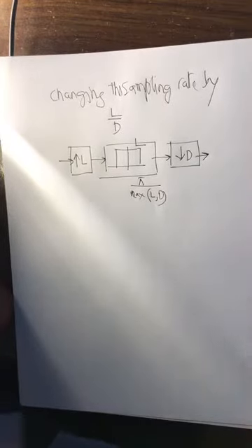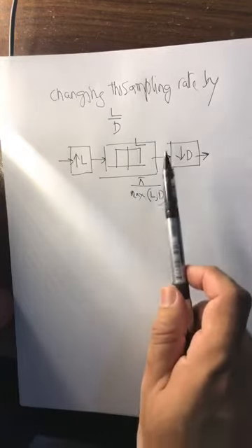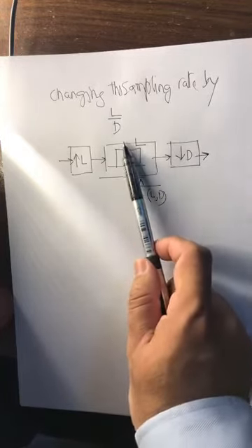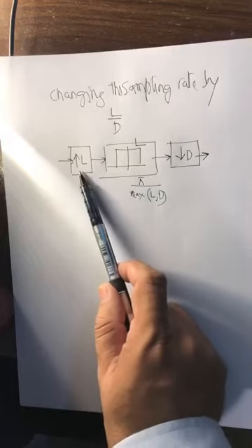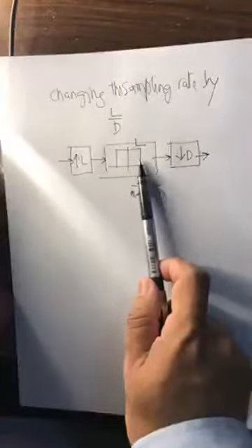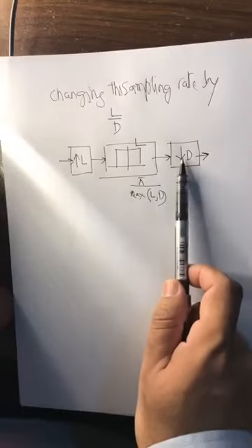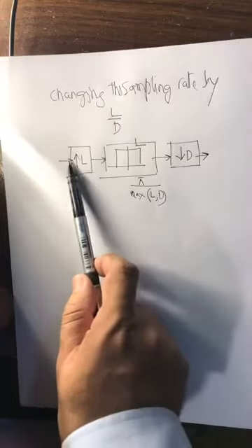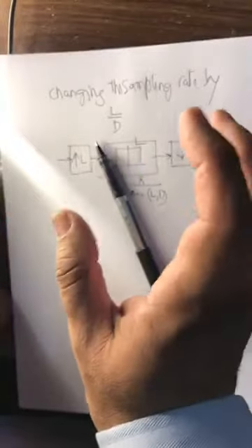So these are the two steps which you need to do if you are changing the sampling rate of a signal by L over D. So you got to first increase the sampling rate by L, then pass it through two cascaded filters, an interpolation filter and a decimation filter, but you can combine them into one filter, then throwing away samples. You take an image and the image size will reduce. That is the only way to perform it in a manner that you don't lose any information.